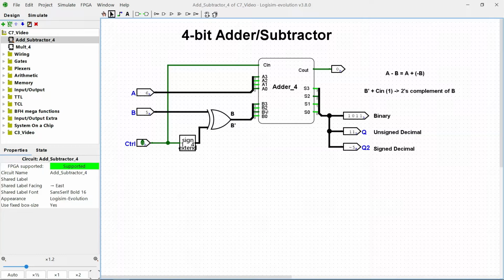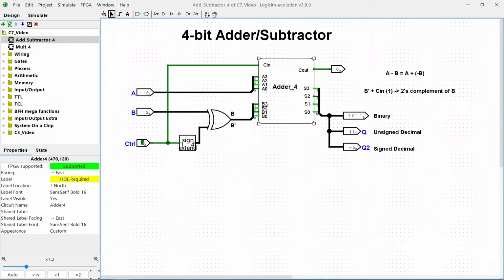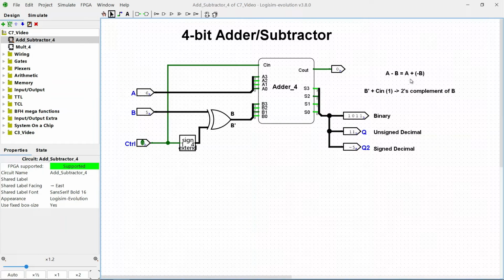So B' will go to the 4-bit adder. At that time, control is also 1, so Cin would also be 1. The 4-bit adder will add A, B', and 1 together. But B' plus 1 is actually the two's complement of B. So we'll have A plus negative B. Actually, A minus B is the output Q. So that is how the subtractor works.